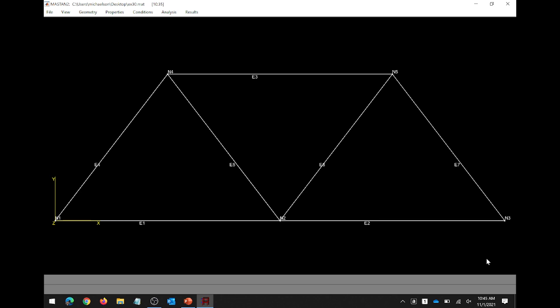This is a very good debugging feature. If your program isn't running, check to see if all the elements are solid. Because if they're not, that means you haven't defined some material properties. Okay? With me so far? All right, I want to stop for a sec. We still have time, and we're going to do this all in lecture tomorrow. But is everybody here? Does anybody have any questions getting here?